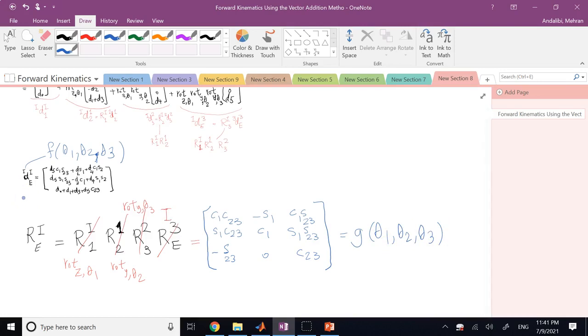They are effective on both of them. As well as, again, you see the geometric distances, D0, D1, 2, 3, all the way to D5, they are all showing themselves in the position, but clearly none of those is showing in the orientation. Because it's just the angles that determine the rotation matrix; the displacements, whether they are variable or constant, have no role whatsoever in the orientation.